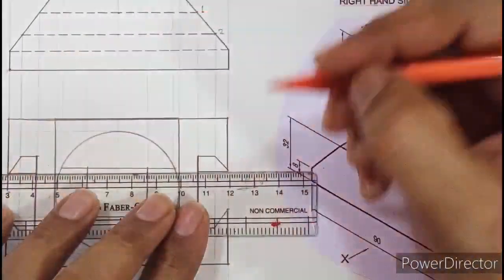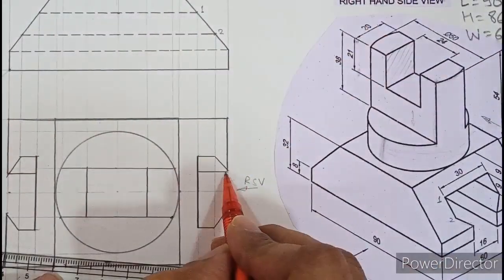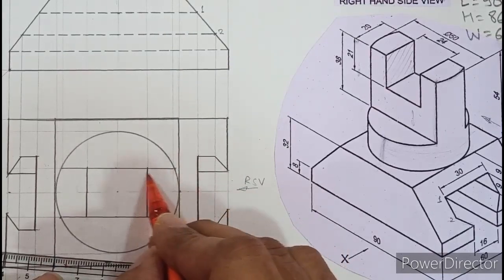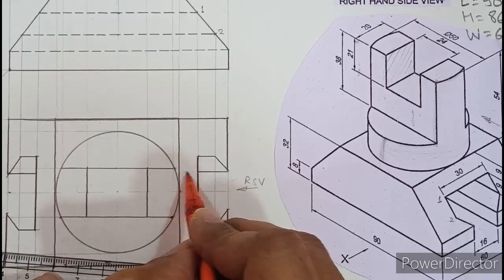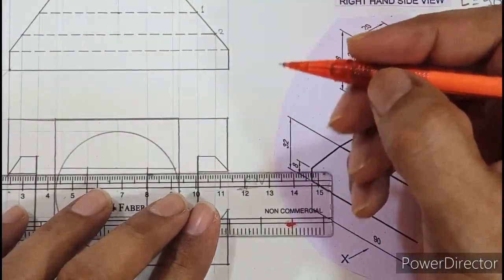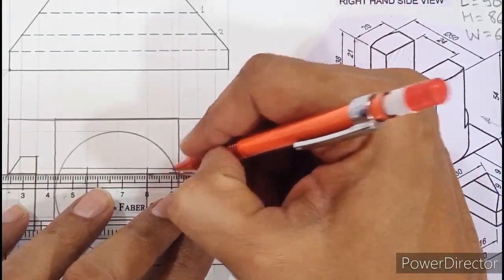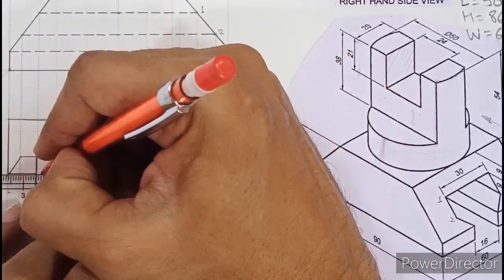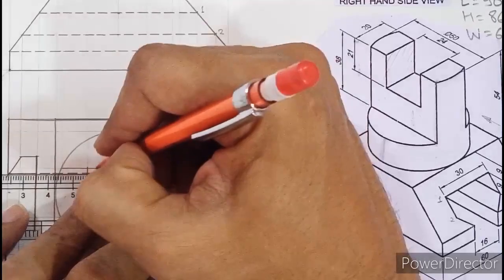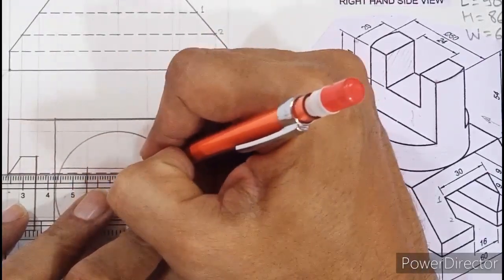Now we know that when dark and dotted line are in continuation, you need to leave some space. So see, there is a dark line over here, what you have drawn, because this much is visible. Now the edge will not be visible. So from here, when you draw a hidden line, you need to leave space. So I'll show you how to leave that space. From this dark edge, leave space of 2 mm approximately, and then you have to start with hidden line like this. So on both sides you need to leave space, because when dark and dotted are in continuation, you need to make out the difference where the dark starts and where the dotted ends.